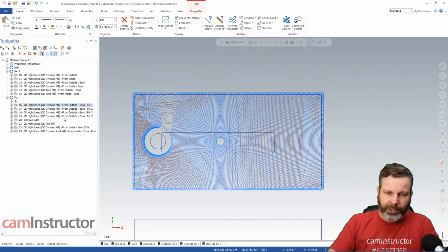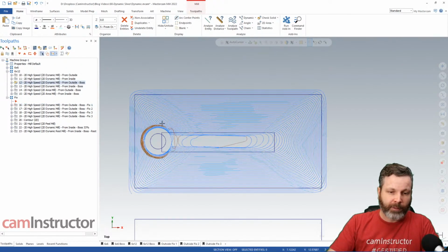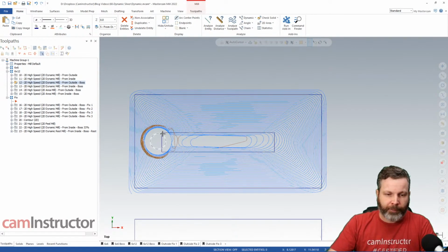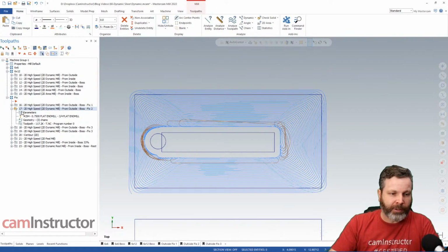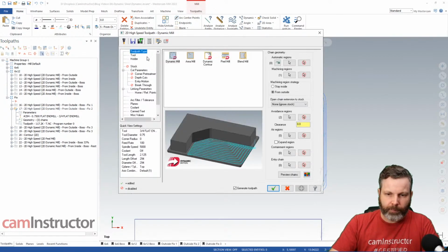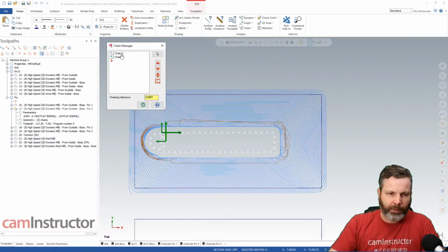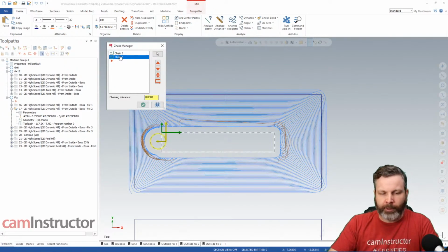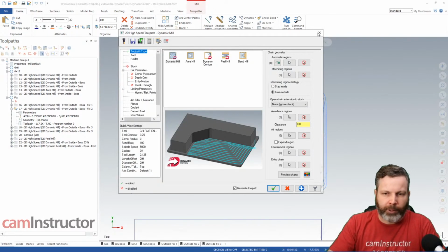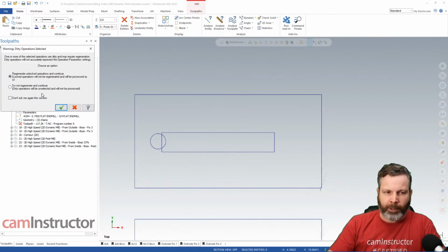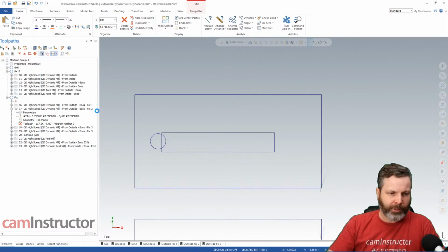So we can just avoid cutting this section altogether. So what I've done here is I've drawn, just freehand, a block that basically encompasses where the sliver would happen. I add that to my chaining geometry as an avoidance region. Up in here, it's in my avoidance region. So I'm avoiding the boss, and I'm avoiding this box that I've drawn in to avoid cutting the sliver. So do we avoid cutting that sliver? Hop into a backplot here. Oh, I made some changes there by accident.